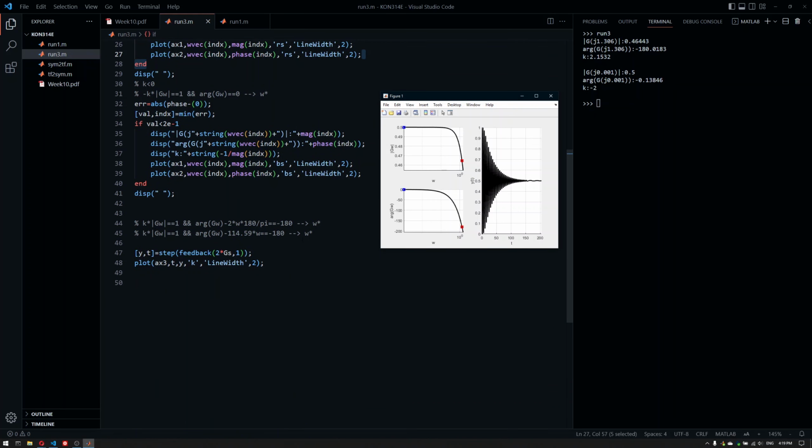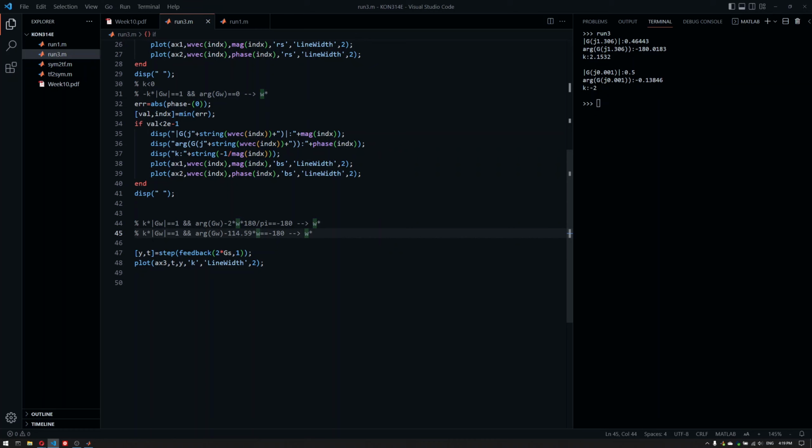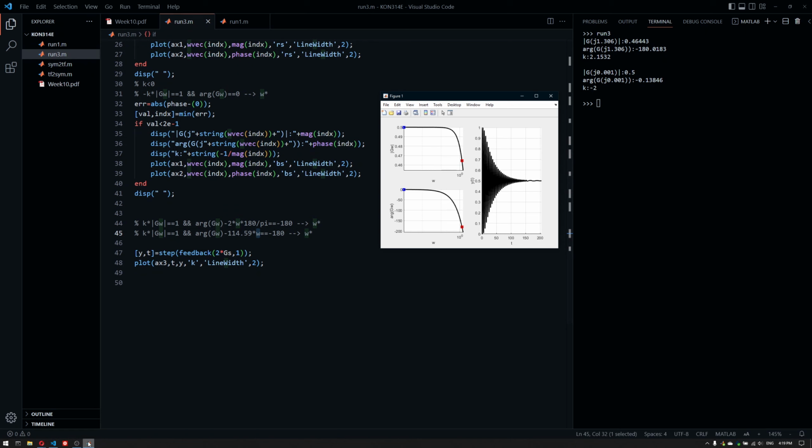What you have to do is write the equation like this and try a certain omega value, look at the Bode plot, what the angle here is, and try to come up with the exact value. You have to iterate a little bit, like plug in omega 0.01 or 0.1, look at the argument of the system. You will see that it doesn't hit 180. If it's less, increase omega. If it's higher, decrease omega, and try to find the actual value of omega that you're interested in.